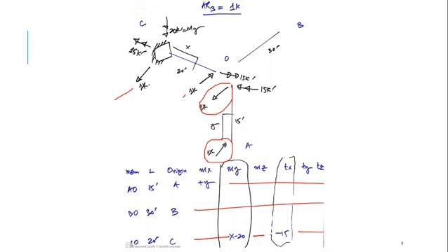Again, this is in z direction and this is in y. So there should be a moment in x direction. Moving this load towards this direction, it forms an anti-clockwise moment. So it should be balanced with a clockwise moment. 1 into, and the length of this member is 15. 1 into 15 gives us 15 kip foot, and this is clockwise.